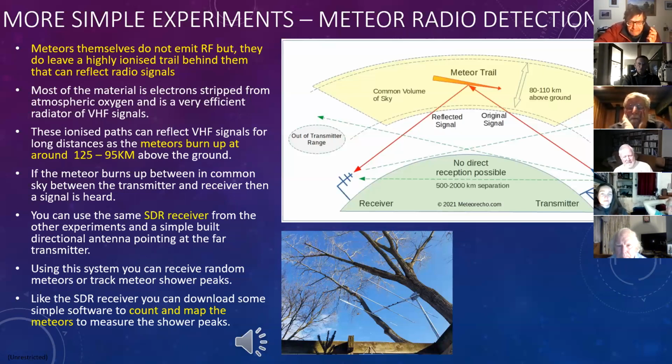The other way is actually what we call backscatter, is that if you had say a transmitter in the North Island and a receiver on the south, those two won't generally hear each other. But if a meteor was to pass somewhere along the path between the two, then the signal will be bounced out to the meteor and back to a closer point.